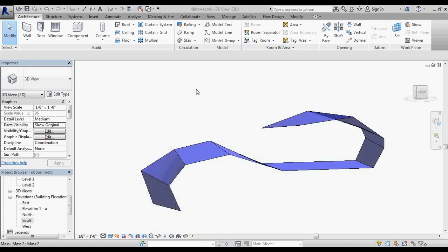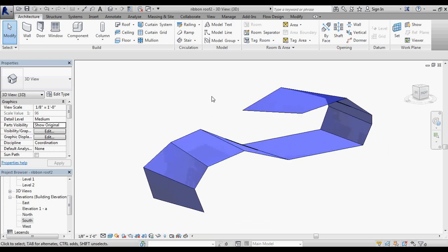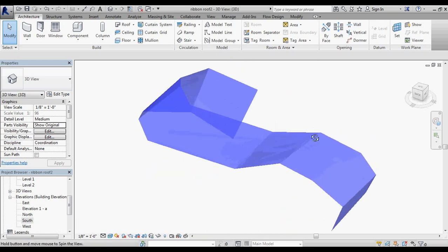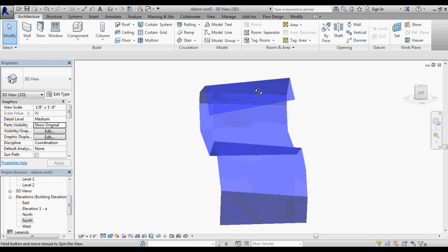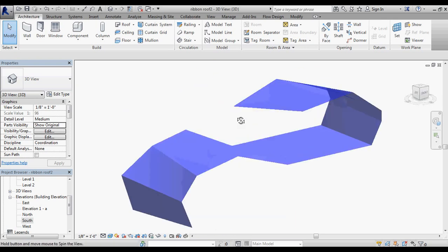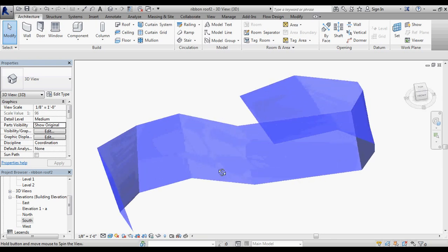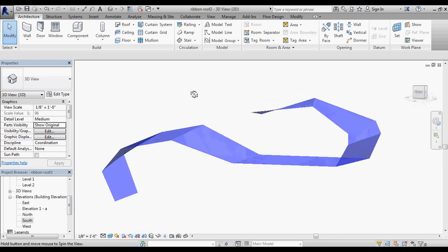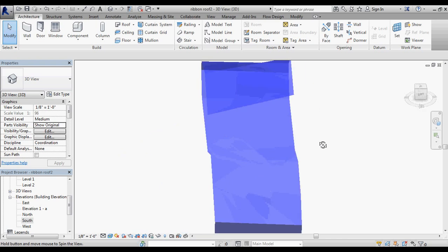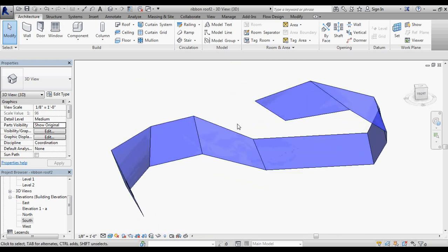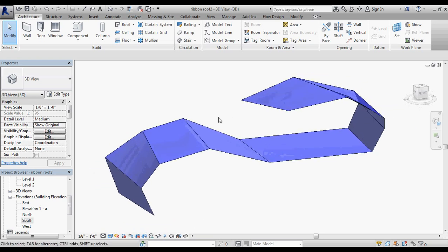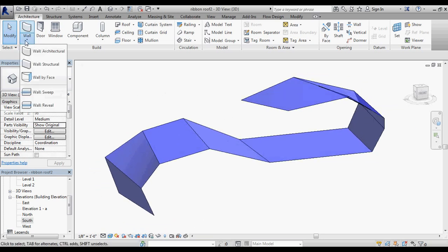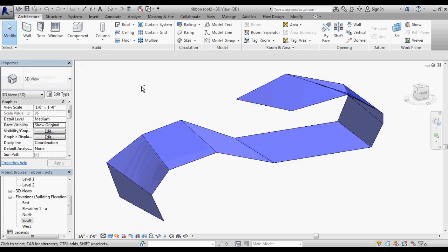So I'm going to call this the Revit ribbon roof epilogue video, because as any of you have probably done that have been working in Revit on anything complicated, from time to time you go back and look at it and think, is there a way that I could have done that better? I wasn't completely satisfied with the results of working with the last system. So I sat back down and kind of regrouped to see what I could do with a different mode of thinking, still using the massing model to build a ribbon, and still definitely using a surface by face. In this instance, I'm going to do the same thing with wall by face, and I'm a little bit happier with the results.